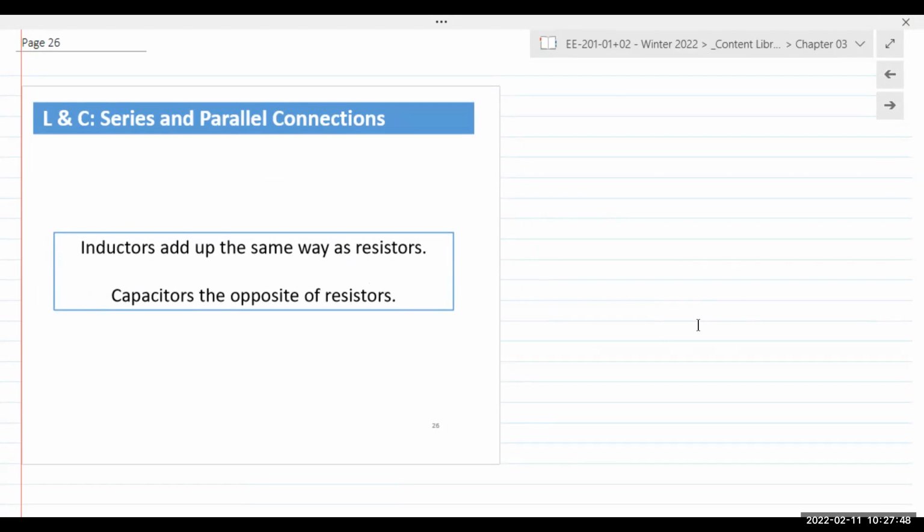If you remember the quiz problem where you had two resistors in series on both sides, on the left and the right, the hint I gave was you can reduce the circuit before you begin your analysis. So you reduce the two resistors to one, thus eliminating two nodes from the circuit. So now if you perform node voltage analysis, you have two fewer variables to worry about, right? So you simplified your analysis.